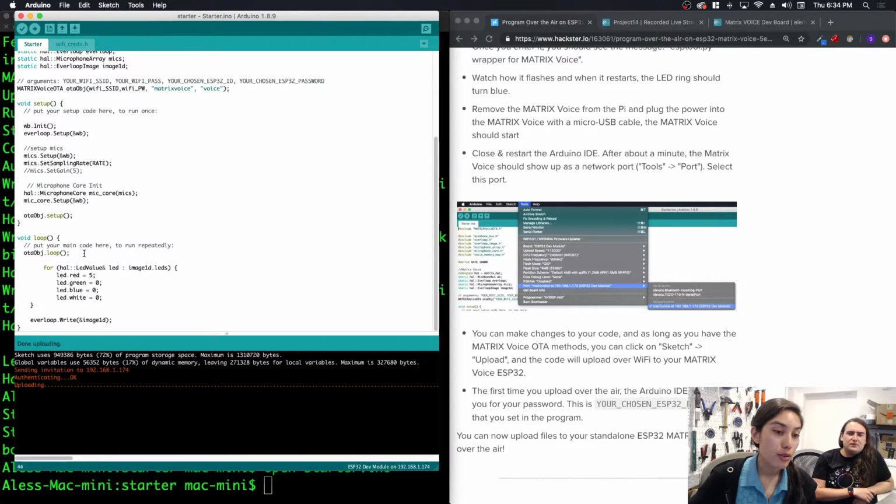So what you could do, which was an idea Boris had, is put the OTA object loop in a check every 10 minutes or something like that. You have a timer. In Arduino you can get timer libraries left and right. There might even be a default one, I don't remember. You can just put a timer and maybe check it every 10 minutes, which might be a little annoying when you upload, because you have to wait.